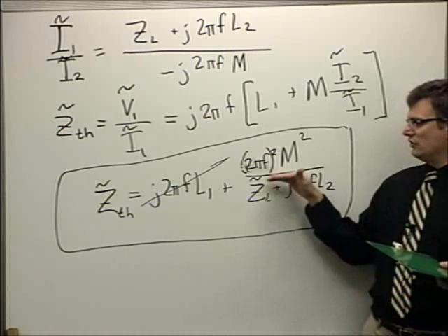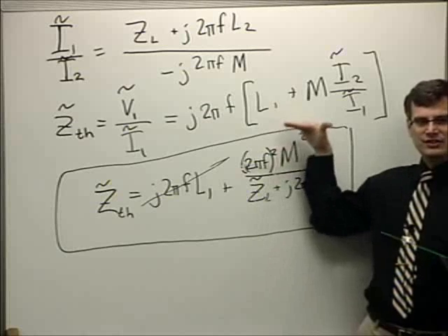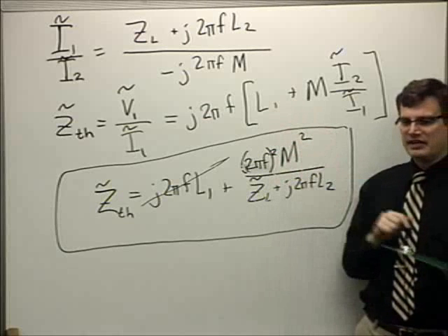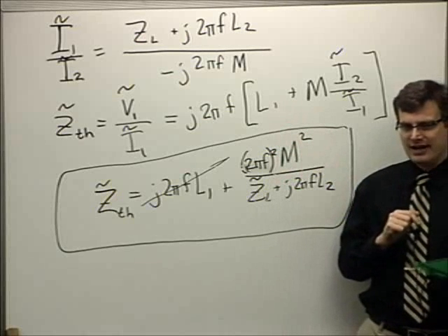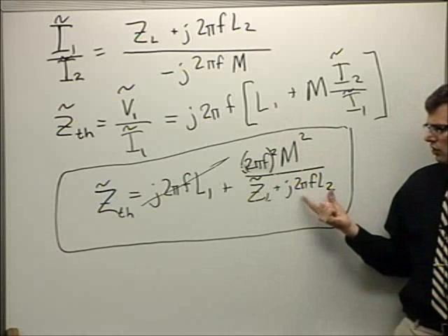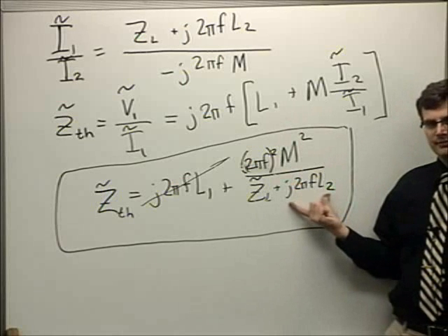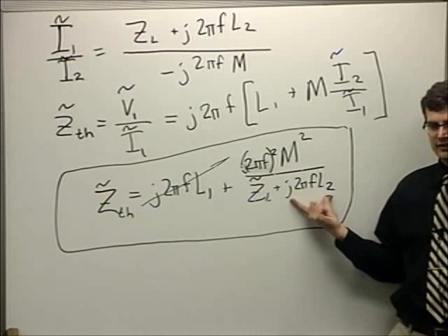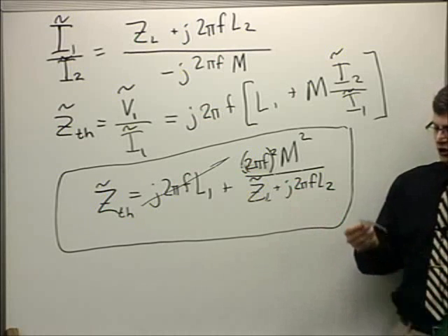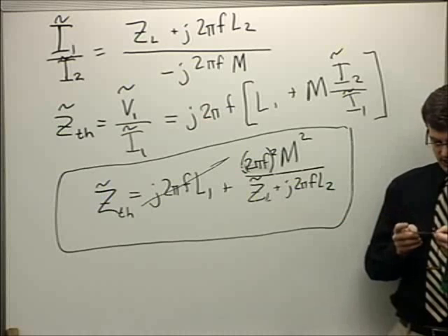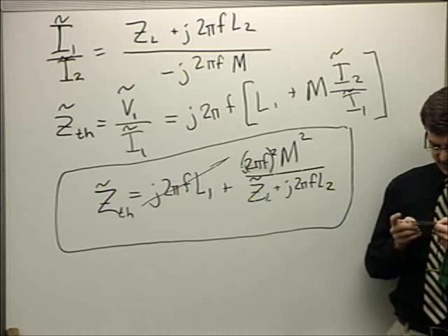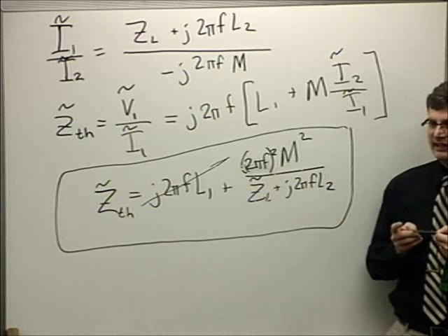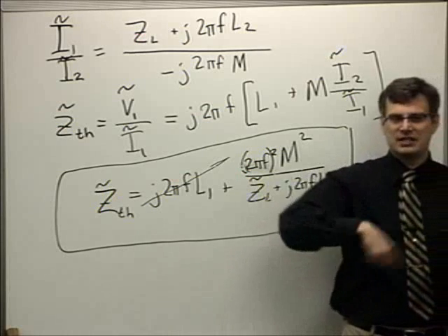And in doing so, you have two different discrete values that you can monitor for the Thevenin equivalent impedance. Now, the one problem that you have with this system is that this term here is highly inductive, right? This is the self-inductance of the reader coil, or of the tag coil, excuse me. So it's a pretty large number because in this case, I've got a card that has 6 windings. You loop around 6 times.